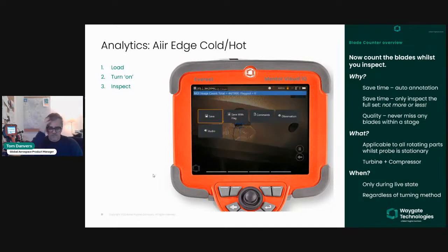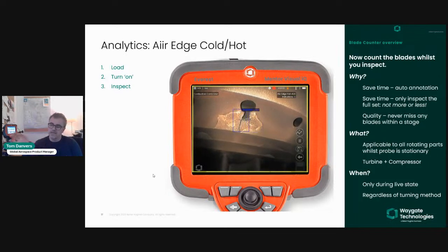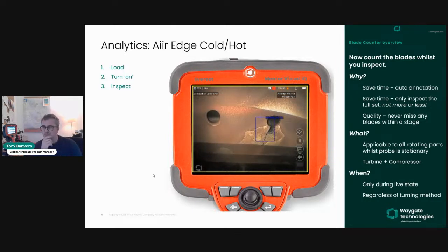So here I've dropped into the combustion chamber and I've just clipped this part of the video just to highlight an area where it found a crack. I actually captured this, and I remember not immediately seeing the crack, even though it's a significant crack, because my borescope was positioned elsewhere. But suddenly all these blue boxes appeared off the edge of the screen before I personally recognized that there was a crack there, and then I moved the borescope up to that area, and lo and behold, you can obviously see a significant defect there. That's an analytic, again, trained purely on aviation hardware.